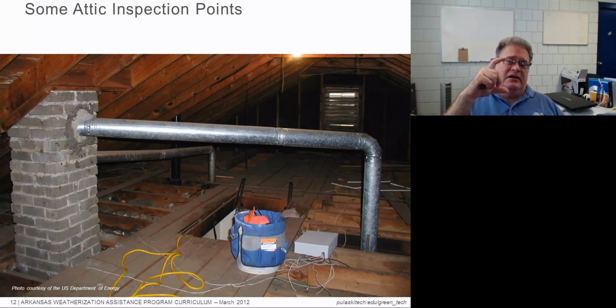And in a year or so, at the most, that's going to settle down, and we're going to have a gap in our insulation there, which means that we can have convection working, and we're not getting full value out of that insulation. So we either need to remove the floor or dense pack under it. We need to do something with it.